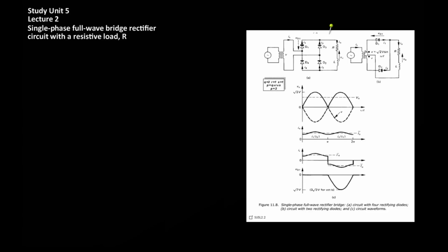These secondary coils need to have the same voltage rating as the primary, and also the 2 diodes which replace the 4 over here need to be able to withstand twice the voltage of the 4-diode full-wave rectifier. This is because these diodes will experience twice the voltage through each switching cycle. Despite being more complex, the behavior of these two circuits is actually simpler than for the half-wave case for an inductive load.